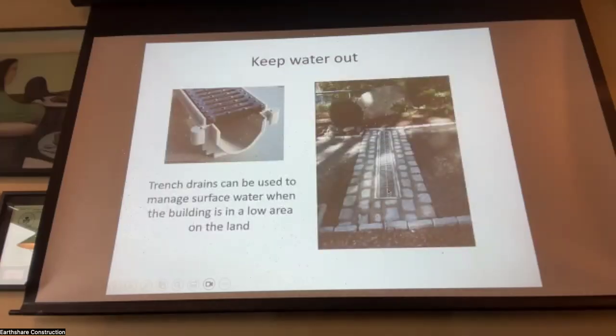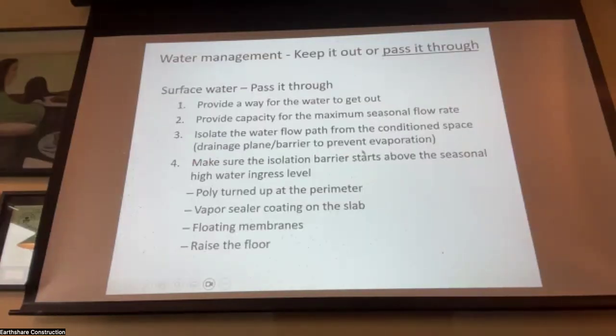Here's an example of some fixes for that. You can put in trench drains that don't look bad. And you can even have them in the driveway where you can drive across. So you want to provide a way for the water to get out.